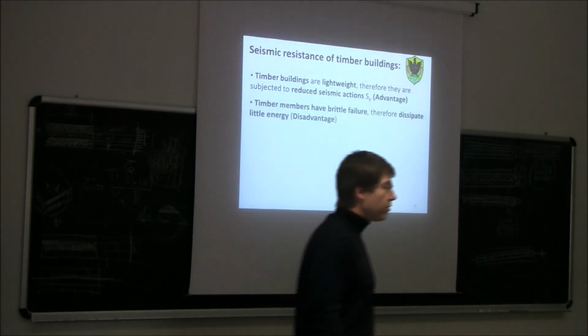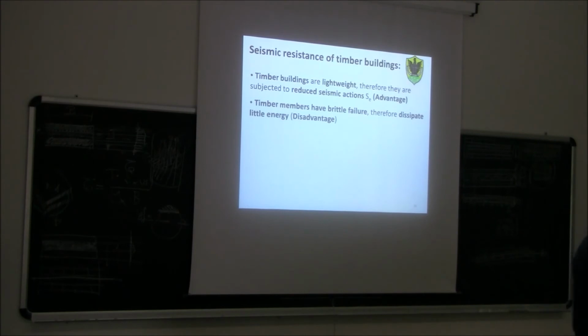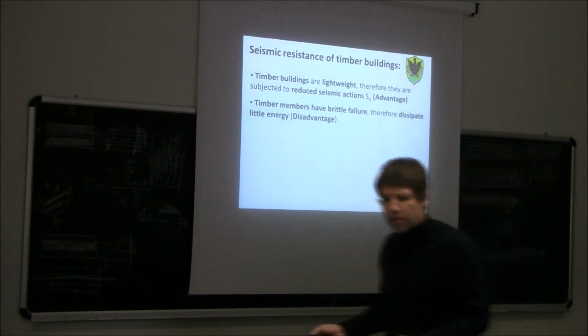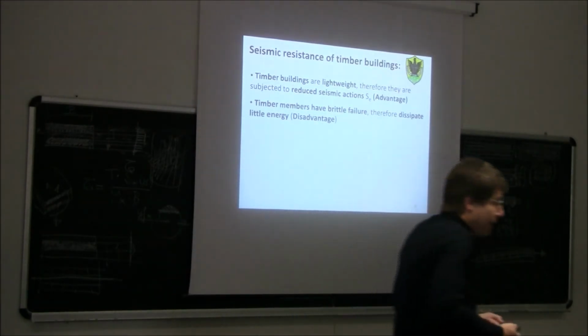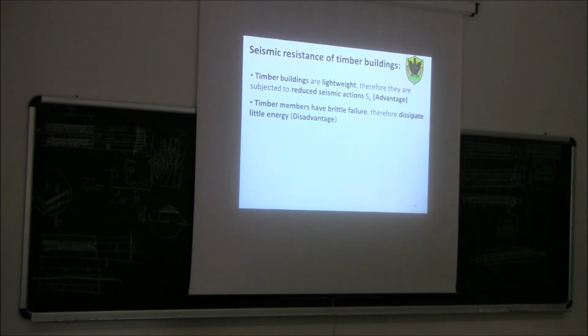However, we also learned that the failure of timber structures in general is brittle. Remember the timber beam that we saw last week? When we applied the load, of course, we had a significant, still an important deflection, but in the end there was an abrupt failure. So, in general, timber members have brittle failure, and so they dissipate little energy.